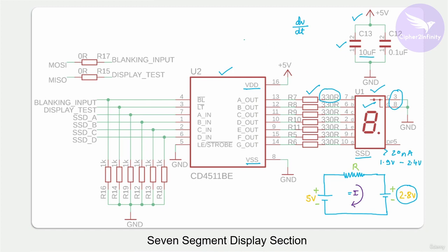If the track which is coming from the PSU, power supply unit, to the IC is very long, I'm talking about the power line, so this is basically the power line. If this track is too long, then you need this capacitor. Otherwise, even if you don't connect this 10 microfarad capacitor, it's completely fine. Without these two capacitors, the circuitry will work without any problem. So you got the purpose of the 10 microfarad capacitor.